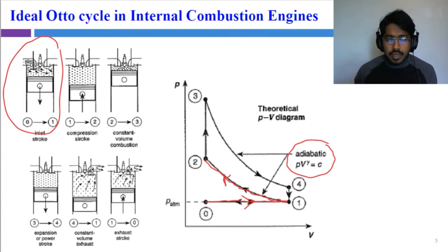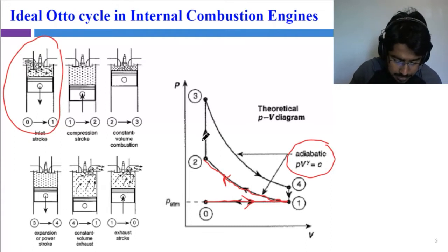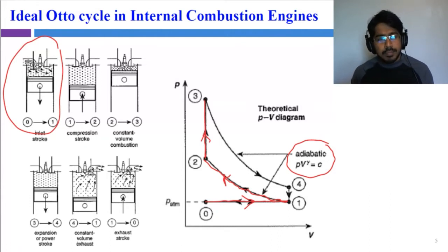At the first instance, when the burn happens, it happens so quickly, the fuel air mixture burns on the spot. Therefore, we can assume for a bit of time the volume is not going to change, but the burning is going to happen. So there we mark this as a constant volume heat addition. With the burning, the temperature increases. When the temperature increases, the gas tries to expand, therefore a pressure buildup, as the volume has not changed yet. Any questions up to state 3?